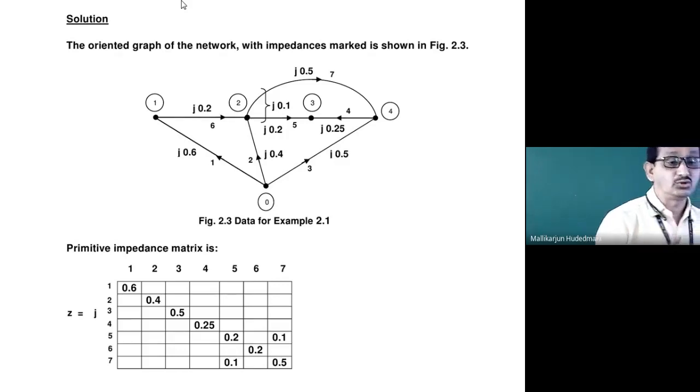If there exists a mutual coupling between any two elements, at least two elements are non-zero in the matrix. Otherwise, if there was no mutual coupling, the empty spaces were seen as zeros only. But there is a presence of 0.1 because element 5 is coupled with element number 7. In this way, this is one coupling. There can be any number of lines coupled to any number of other lines. Then that many non-zeros are present in this matrix.